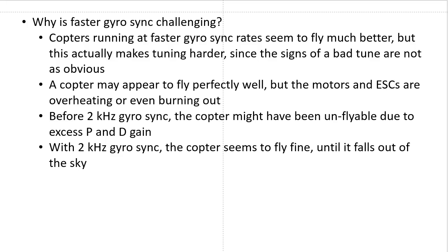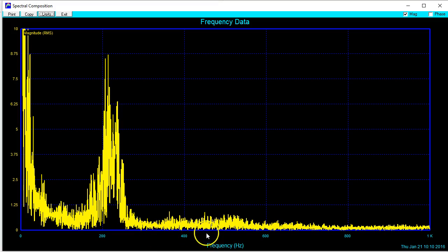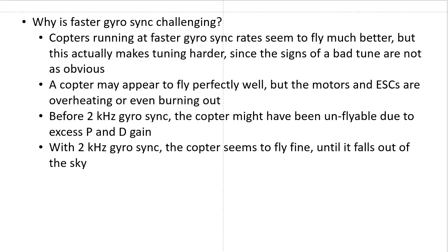As we get to higher sync rates, as I suggested, I also feel like there's going to be a law of diminishing returns here. And we may find that at the higher sync rates, it makes sense to just make an informed decision about how to get rid of some of that data and say filter it down with a low pass filter or something. Because do we need 4 kilohertz frequency components fed into the PID loop? Probably not. I hope that was helpful.